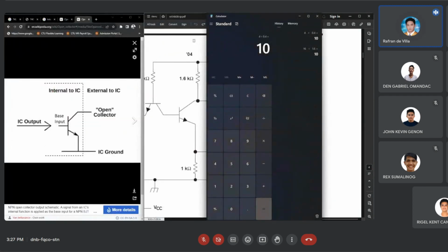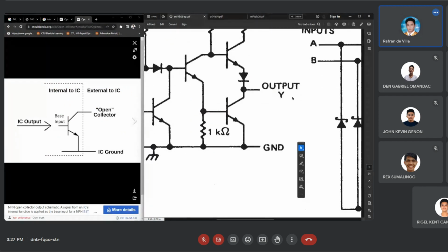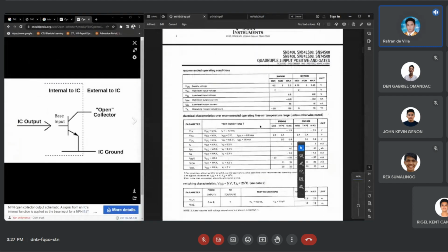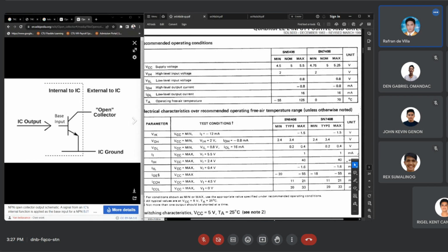So, let's say for example, let's try to check out 7404. Okay? Try ko nun yung solve, guys. Base ani nga specification sa 7404. Okay? Assuming that the output of my 7408, di, not 7404, 7408, is to be connected to the input of another 7408. Base sa specification niya, pila may fan out niya? Pila man kabuok input sa 7408 ang kaya niyang ma-control reliably?